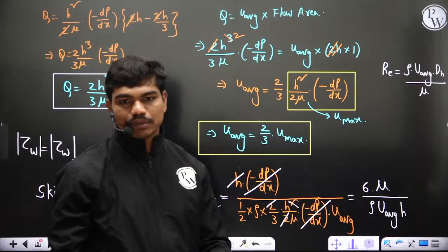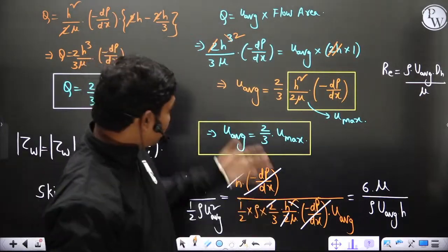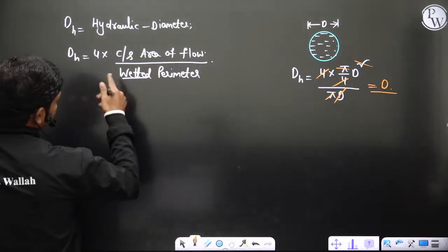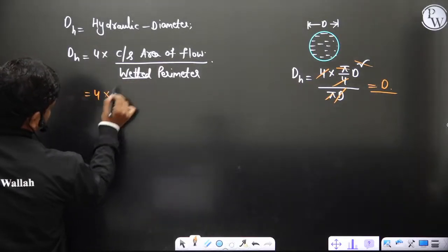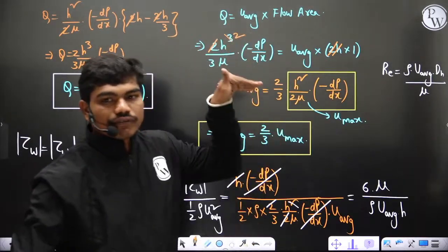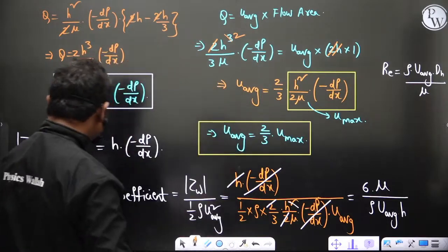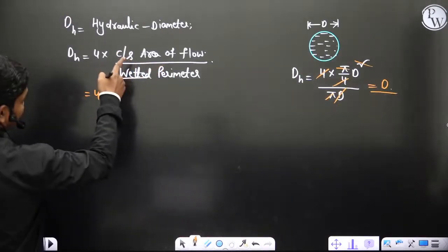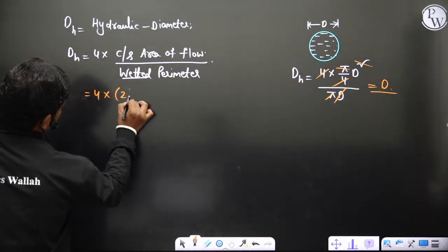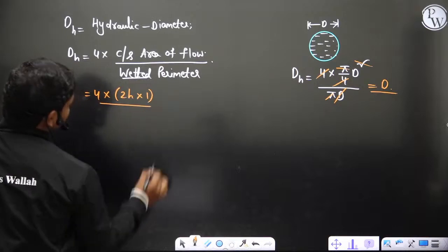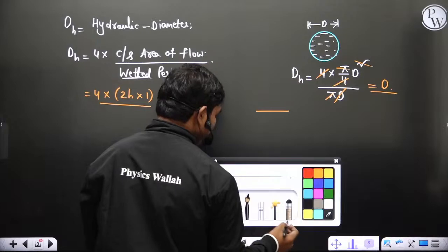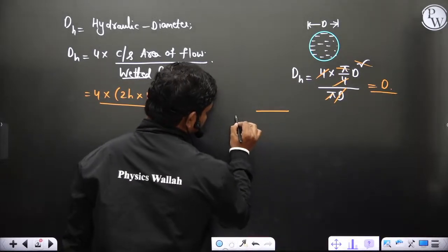Okay, but let us suppose if they give you square pipe or rectangular pipe or maybe some channel like this, how do you do? Look, 4 into cross sectional area of the flow. Now this spacing is 2h, width of the plate is w, then clearly what happens, this cross sectional area of the flow is like 2h times 1, for example, by wetted perimeter. So wetted perimeter is like, see, this is the channel. If you take the side view, here we are leaving it.